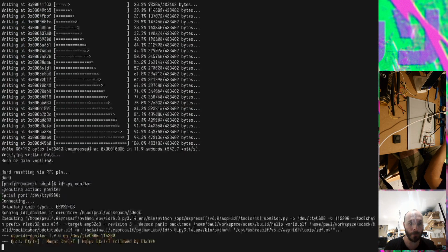But yeah, it looks like I don't need this, so I can keep the resistor there, sure, why not, it doesn't matter. But it has an internal pull up already, which means that I can actually wire it to ground, because that means that when I press the button, it'll just go through the pin through a resistor. I think that's the idea.